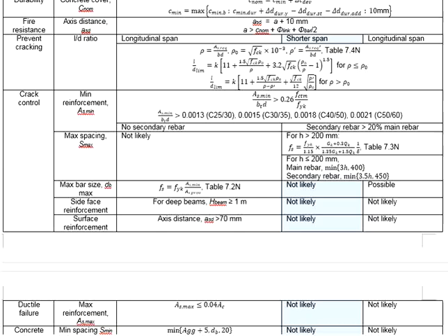In order to have as much bar area as possible, the designer can choose to provide large diameter reinforcement bars, such as 2H25, 2H32, and etc. It is likely that the maximum bar size is exceeded under such circumstances. Therefore, you should check for the maximum bar size for a beam.